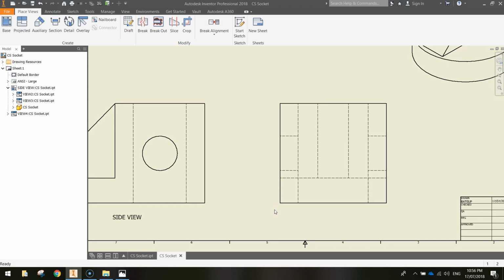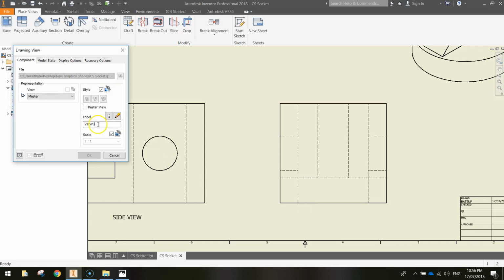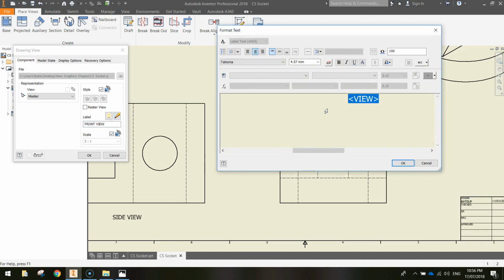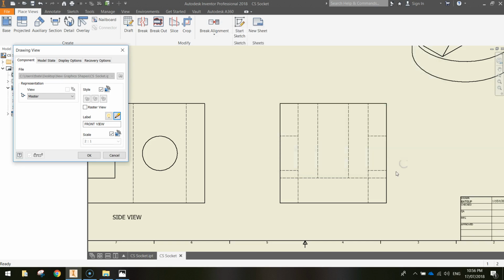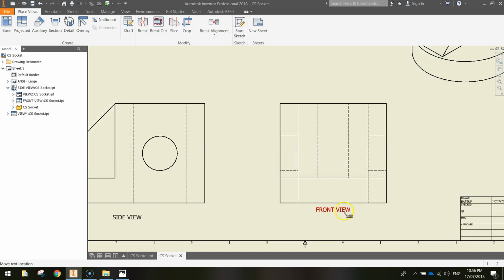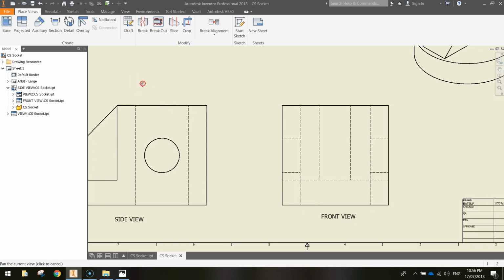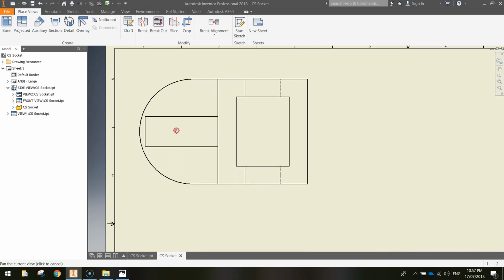Okay, the one over here is the front view, as if we're looking front on at the shape. So let's double click on the dotted red line and write in front view. Toggle the light bulb on. Hit the pencil and delete scale, highlight the view and make the size 6.1, click OK, click OK. Sorry if I'm going a bit quick here, but we've done this before, so hopefully you know exactly what you're doing.